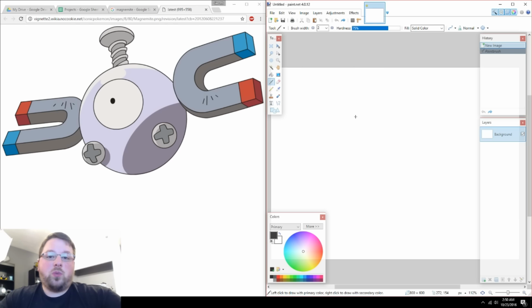And now this is the point where you really need to determine what you're modeling this for. And really what you need to keep in mind is how you're going to print it. And there's a few different ways you can do it. You can just model the whole thing and then just load it up with supports and print it as one object and just have to remove the supports and clean up the areas around that. That's a totally viable way of doing it. Otherwise, you can slice the model up into smaller pieces that print more easily.